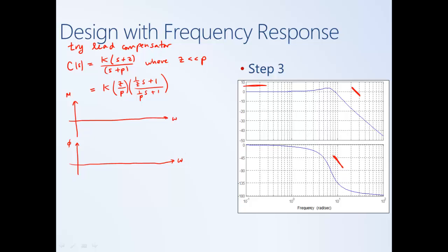Okay. In general, the way that we could plot the Bode plot is as we've done before. We can plot it component by component. So plot the Bode plot of a gain, plot it for a simple zero, plot it for a simple pole, and then add them up. I'm going to go ahead and do it all at once. If you don't exactly follow what I'm doing, you can always do it yourself, component by component, then add them.